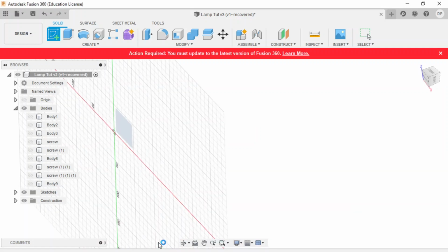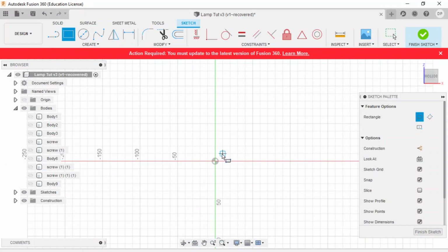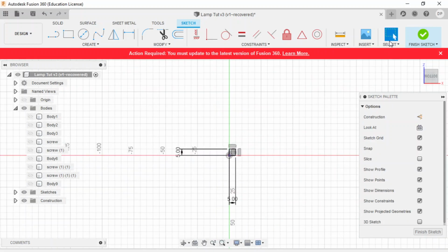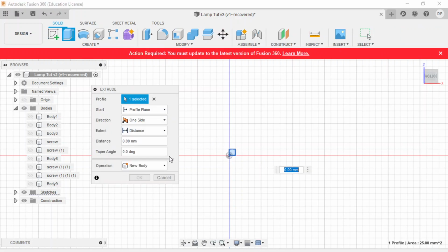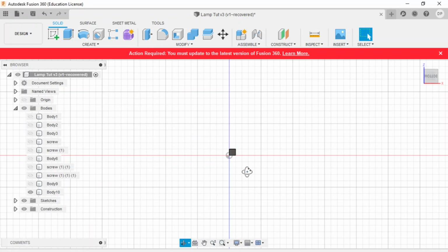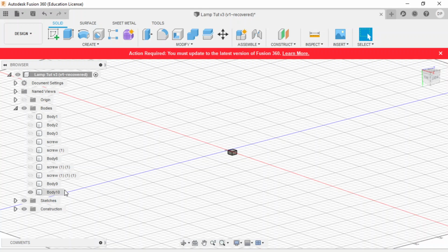Let's go to here. So we're just going to make a new part. Let's say our LED light is, I don't know the actual dimensions of the LED lights. What do they look like? About 5 millimeters by 5 millimeters. So about 5 by 5. Cool, enter. And then I want to extrude it. And they're about 3 millimeters high. I'm just guessing this. You'll obviously be measuring your own ones. So we have this lovely little cube.